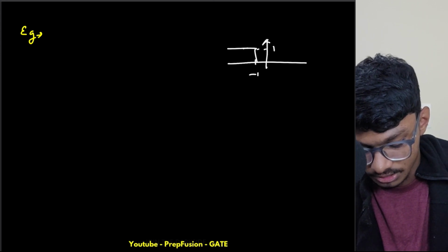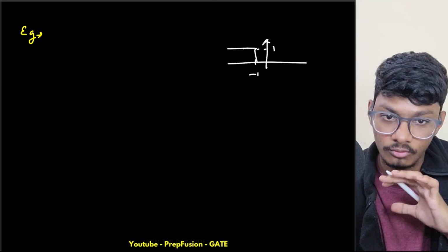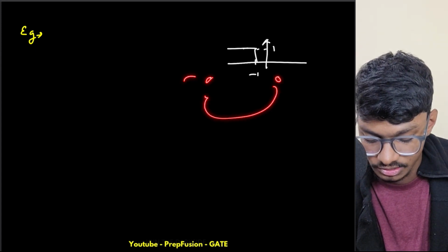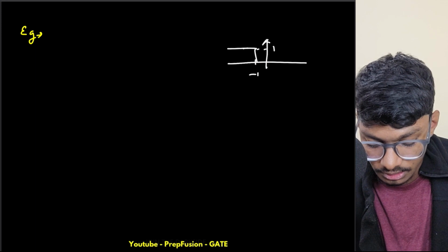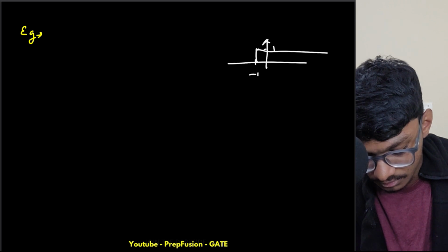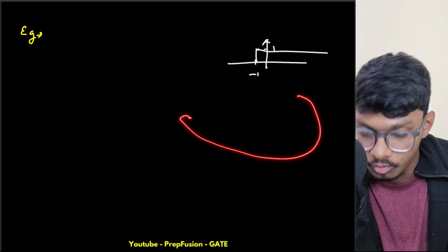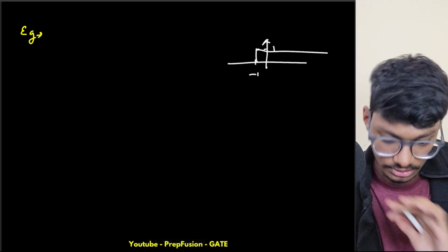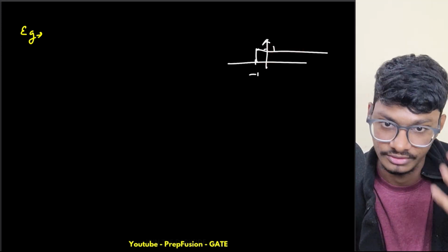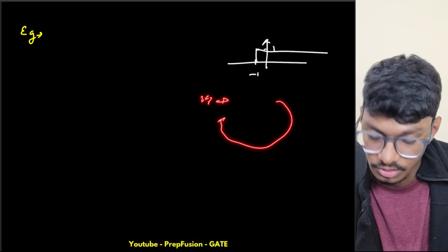This is on and this is off, 0. Now what will happen when my input is, let's say I want 29 degrees, so the input is 29 degrees and the output reaches 29 degrees, the error signal is 0. Sorry, I made it wrong again. This will be like this. So my input is 29 and the output has reached 29. Let's say the heater is still on, that means the error signal is 0. Now obviously the temperature will further increase, so the error signal will reduce further, because the input is still fixed at 29 and the output is going towards 30.